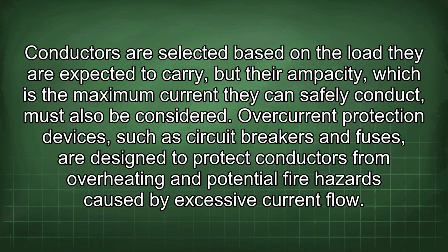Conductors are selected based on the load they are expected to carry, but their ampacity, which is the maximum current they can safely conduct, must also be considered. Overcurrent protection devices, such as circuit breakers and fuses, are designed to protect conductors from overheating and potential fire hazards caused by excessive current flow.